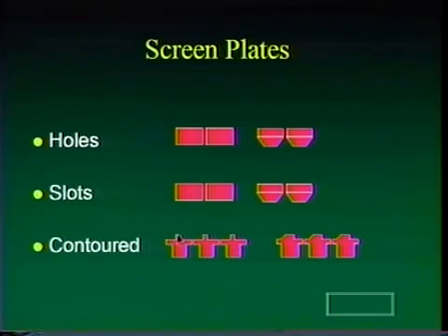They disrupt the pulp mat, and by disrupting the pulp mat you can get better throughput through your system. The microturbulence also gives you some agitation here, and what it can do is take those contaminants that are one-dimensionally or two-dimensionally smaller than that slot, realign them and allow them to pass through.